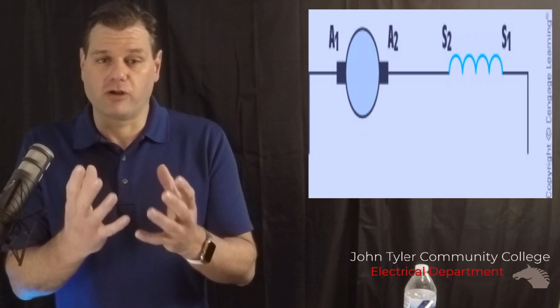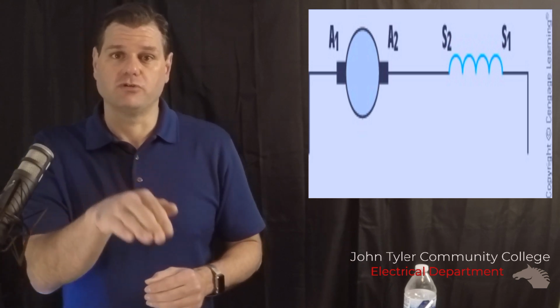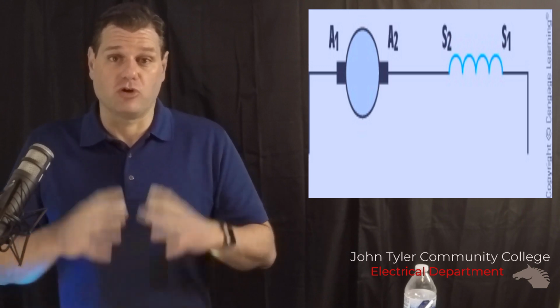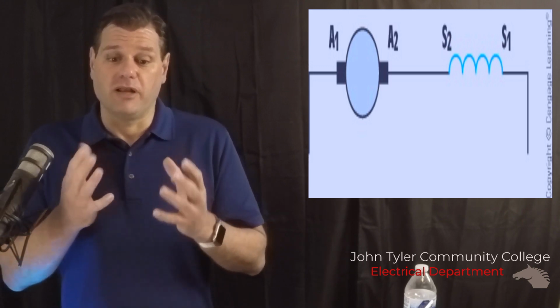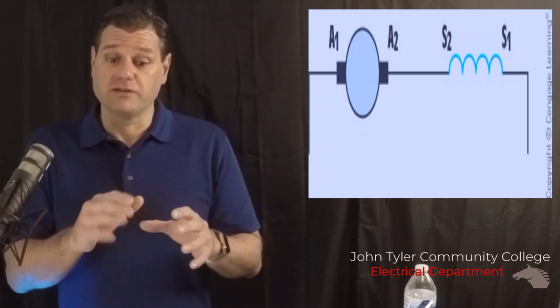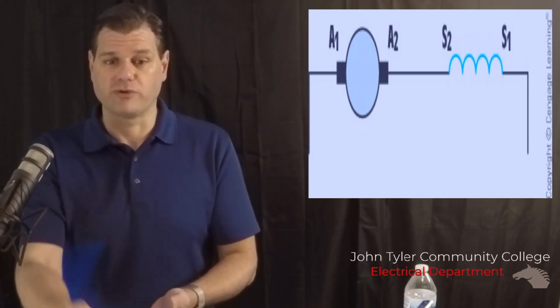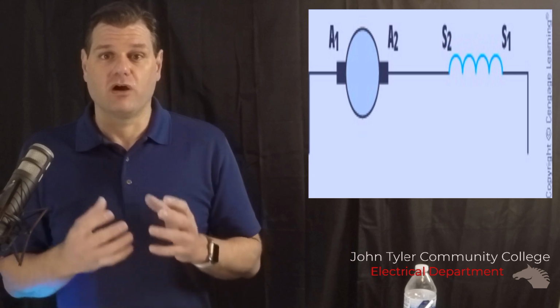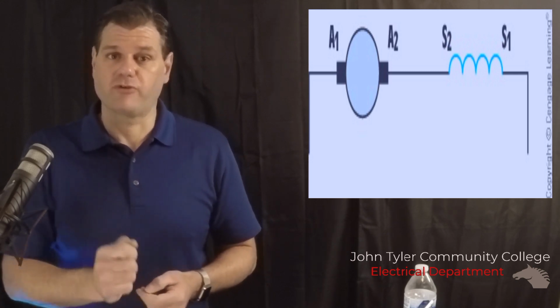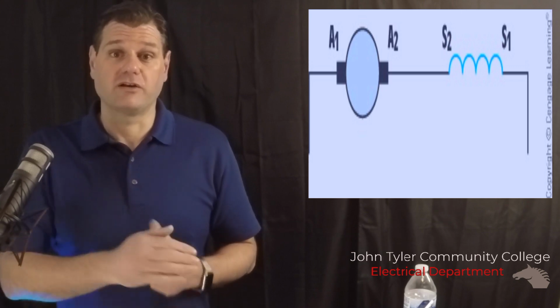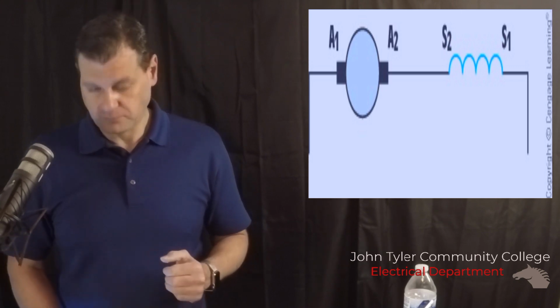So if you put a very large electrical load on, it will start to dive down, and it's one of its weaknesses. So it can produce a whole lot of voltage for its size, for what it does, but it's going to start diving down once you add more electrical load, more light bulbs, more resistors, more stuff. When you're plugging things into it, refrigerators and plugging stuff into your generator, it's going to eventually pull it down and down. So it's not going to be efficient no more.